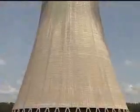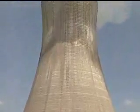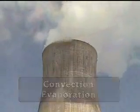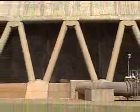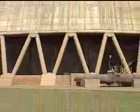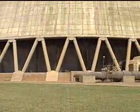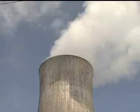In a cooling tower, heat is removed from the water in two ways: by convection and by evaporation. Convection is basically heat transfer to or from a moving fluid. In this case, convection occurs as the cool air flows over the water. The movement of the air causes heat to transfer from the water directly into the cooler air.